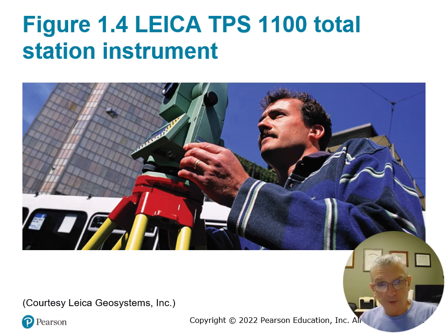Here is a picture of a total station. A total station is an instrument that measures angles and distances. Most all of them that I know of that are manufactured now are all fully electronic. They don't require any interpolation, reading of any dials or anything like that, and they will transmit. Used to be through cords, now they're basically all Bluetooth to a data collector, controller, electronic field book, whatever term you might like.